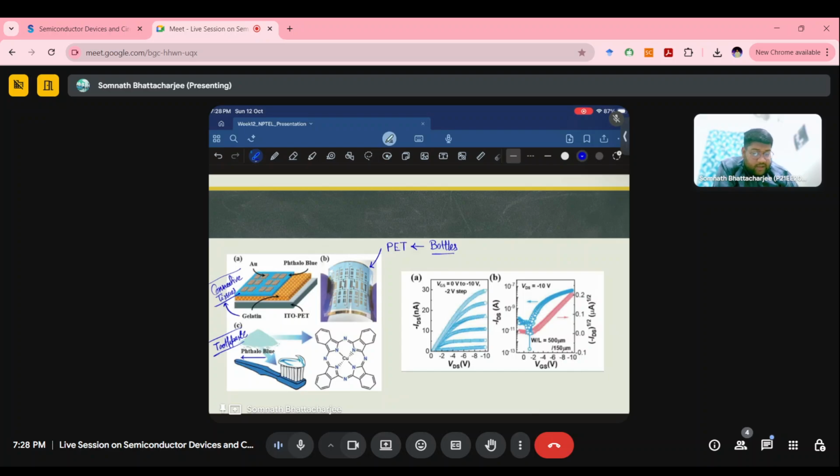So this was my device, and you can see from here as well, the current is in a range like this. My saturation current was here, that is obviously less than 10 to the power minus 7 amperes, obviously in the range lesser than a microampere. So you can see that these devices are working in a range of microamperes, whereas if they could work in a milliampere range, it would have been a very good performing device.